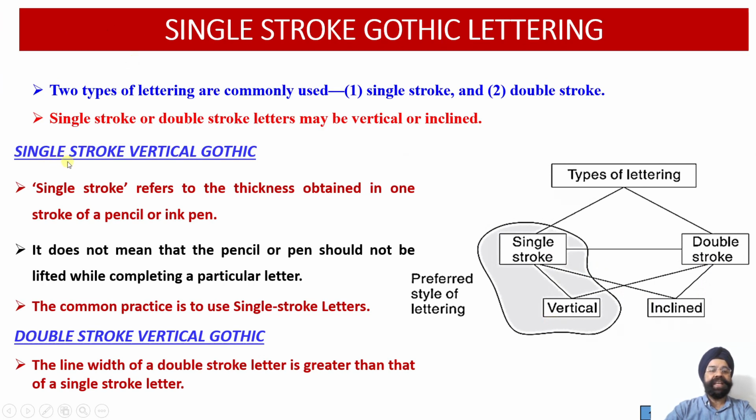Now let us start with single stroke vertical Gothic lettering. The single stroke means that the thickness obtained in one stroke of the pencil should be there.